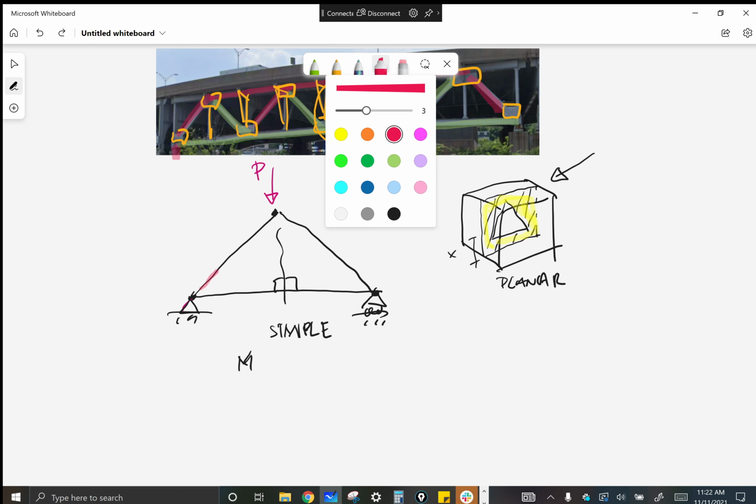That we can commonsensically say this is in compression, this is in tension. They are equal and opposite to each other, or they're not equal because we're going to do the trigs. They're not equal, but they are in opposition to one another. And so in simple planar truss theory, we say these are two force members, because since it's just a plane and there's only one point of material could go through, it's going to have to either go this way or this way. It's going to have to be either in compression or tension.